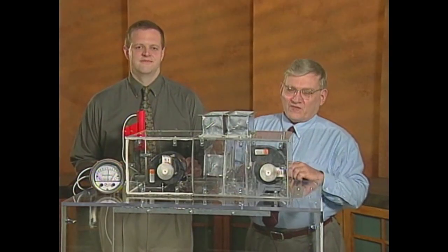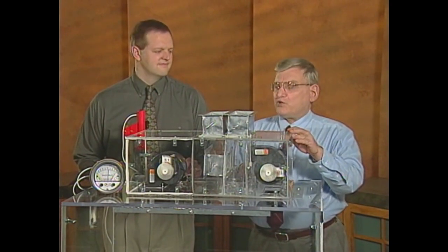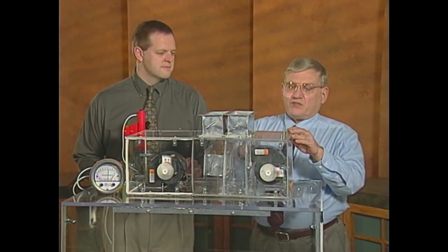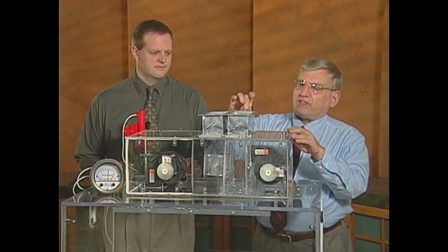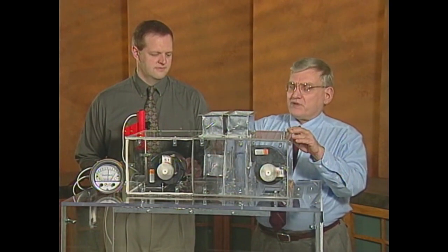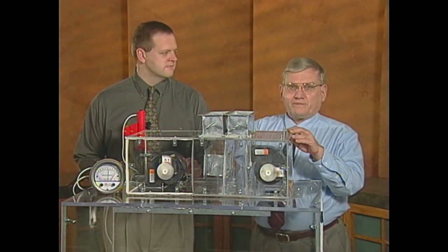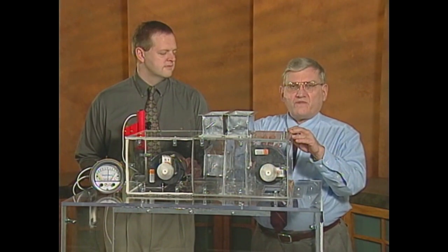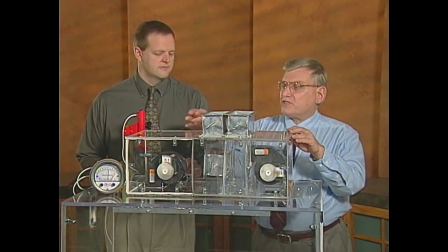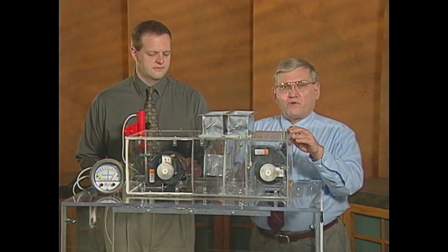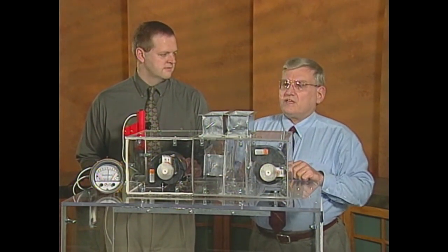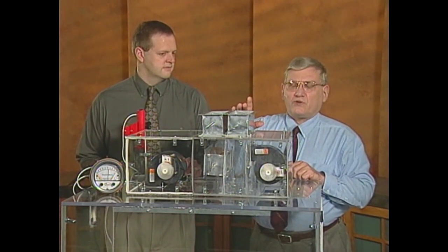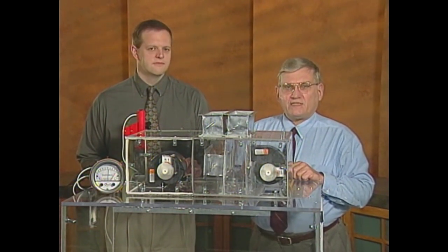Art, can you and John demonstrate this one? Sure. We've replaced the relief fan module with the return fan module. The return fan is now in series with the supply fan. We have a relief damper, an outdoor air damper, and a return air damper. The return fan air volume can be offset from the supply fan air volume to allow for remote exhaust and exfiltration. In a typical unit, the outside, return, and relief dampers would all be linked together.